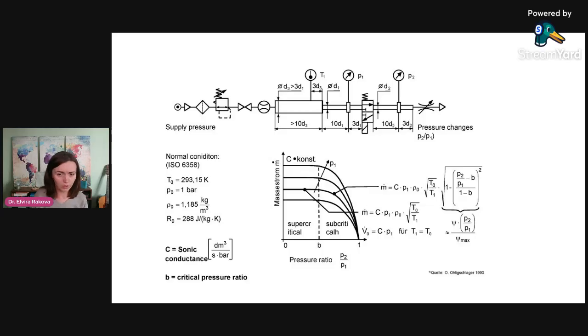Sometimes it's even better to have a bigger pipe, and I'm talking about the big distribution system from the compressor room, a bigger pipe in case you want to add more production lines, right? So you're adding more production lines, and of course it's better just to be on the safe side and have the bigger pipe. But here we go into a very interesting moment, because some people will think, but I actually need to fill all this pipe with compressed air, meaning that I need a bigger compressor.